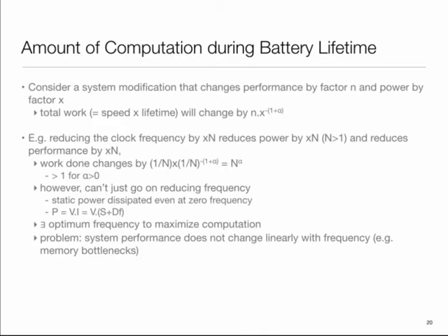More recently, there have been models which capture other aspects. What's the voltage of the battery? What is the capacity? Because in many apps voltage matters, as well as the cycle life of the battery, that is, how the battery ages. On the computing side of the story, unfortunately, those models are not very useful directly. That is way too complicated. So things like Peukert's formula, or what we are going to see next time, something called the Rakhmatov model, are attempts at coming up with compact models which are computationally better and easier for us to deal with, and which we can use during our design process.